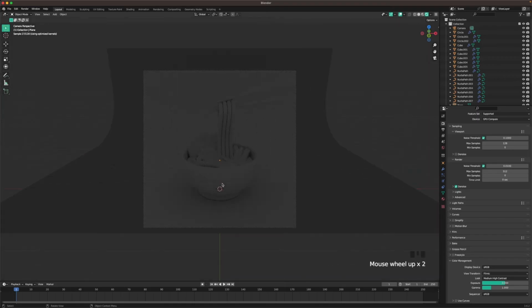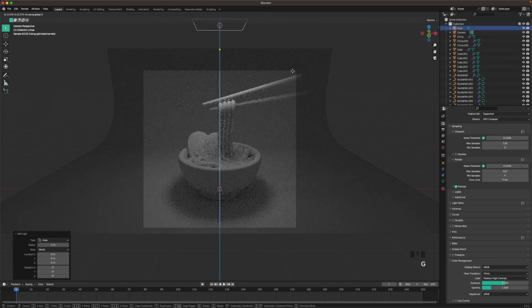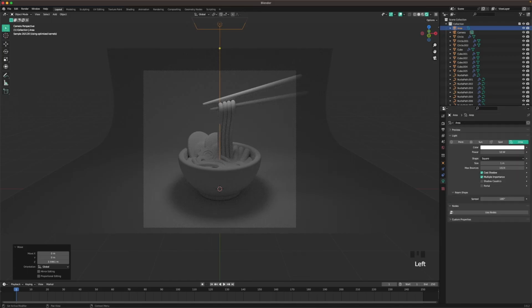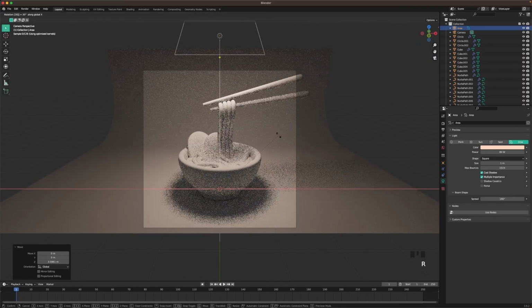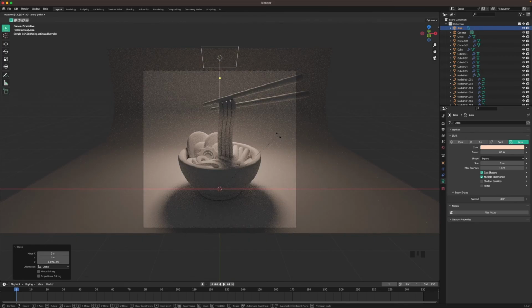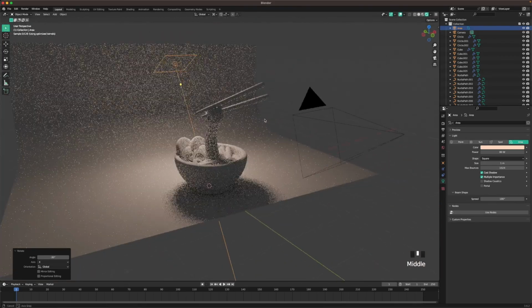And then we'll start adding some light. Press Shift A and then add an area light. Press G and Z, move it up. And then go into your light settings, and then we'll add a slight color, which is FFD8C0, and then we'll increase the power to maybe something like 80. Yeah, that looks good. Press period and change your pivot point to 3D cursor, then R X and 30 minus to aim it from the back.